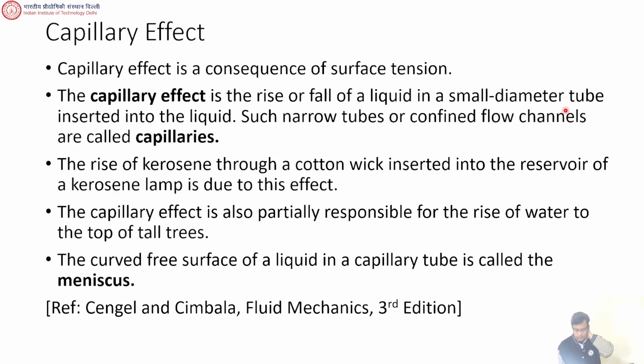Okay, so capillary effect is a consequence of surface tension, and if you have a smaller diameter tube, then the rise is higher. Also, some examples: if you place a cotton wick in a kerosene reservoir, then the kerosene will rise up the wick. Okay? So in a candle, what happens is that because of the presence of the flame, the wax melts and then it gives you a liquid wax pool, which will, because of capillary effect, rise using that wick.